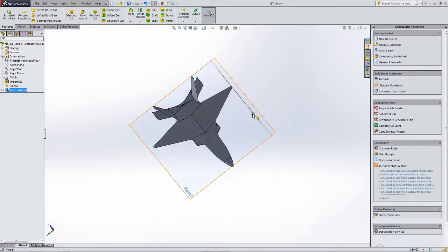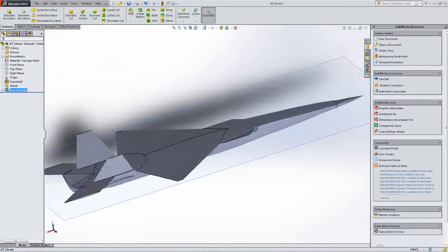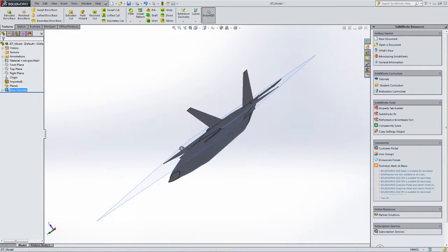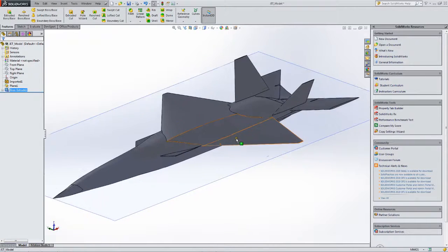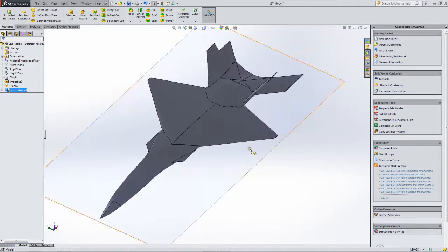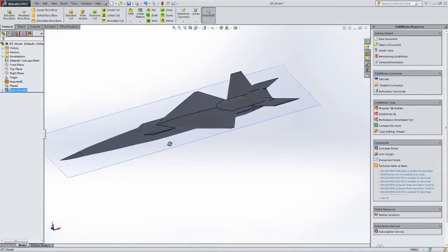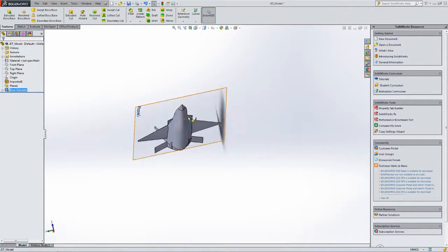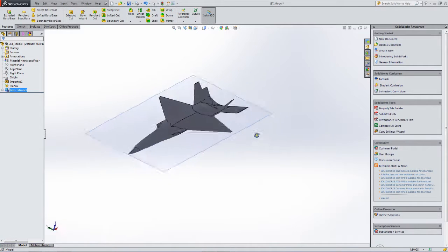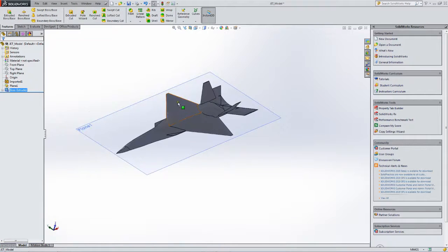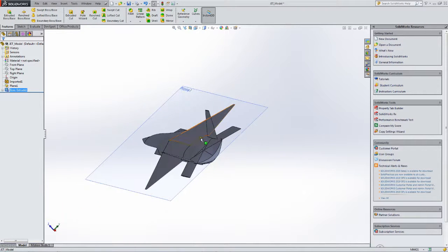As I say, putting inlets on the model kind of messes up the drag and may even mess up the lift. So we'll get a cleaner estimate of lift and a reasonable estimate of drag from this model with the strakes that I've created, and without the actual inlet shapes. The reason for that is because there's flow through the inlets, and then there's engine boundary conditions and all kinds of things that complicate it.